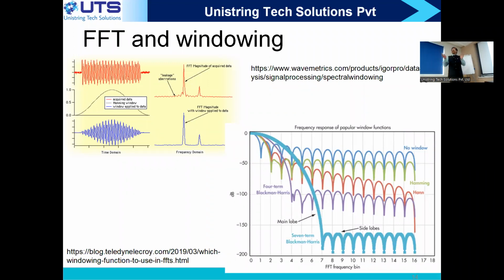Continuous time Fourier transform is a concept, the ideal equation to understand the conversion; it is not implementable. In continuous time, the time is actually of infinite precision. Discrete time Fourier transform is its modified version which is implementable in your processors, FPGAs and all.